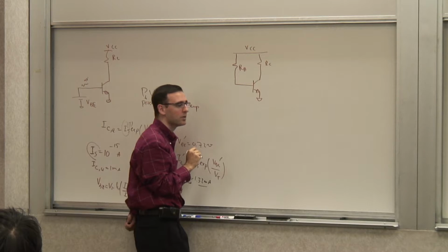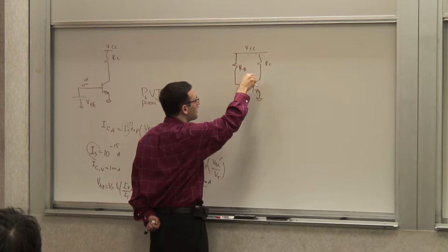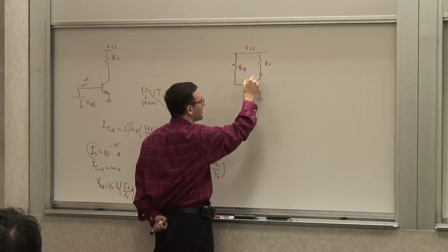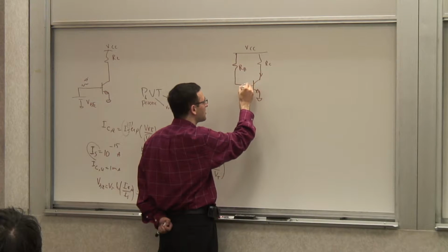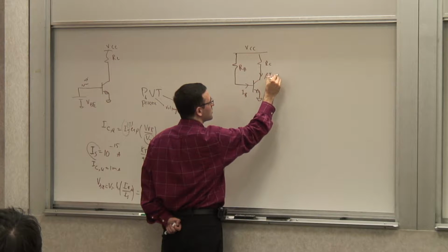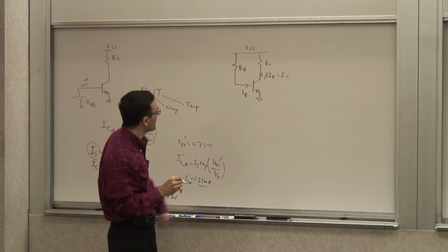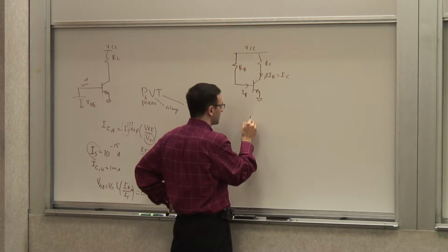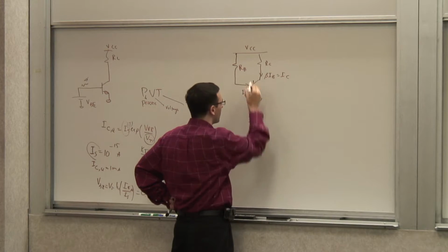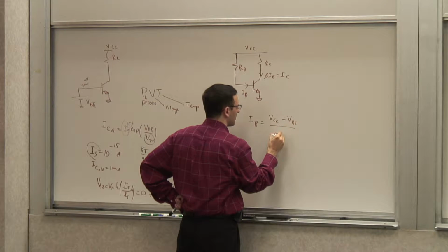The next step would be to use a resistor here and connect it to the supply, so this current will determine that current. For as long as the transistor is in the forward active region, if this is IB, this will be beta times IB, which is IC. So what is IB in this case? IB is this voltage, VCC minus VBE, over RB.